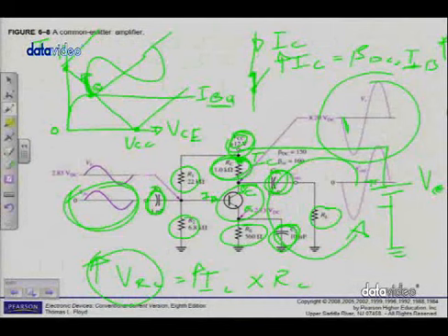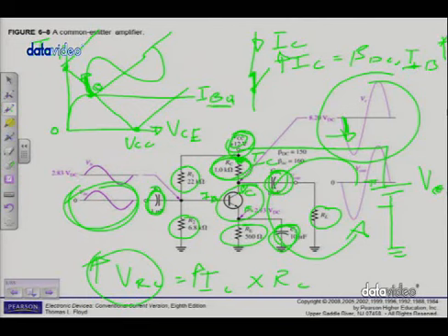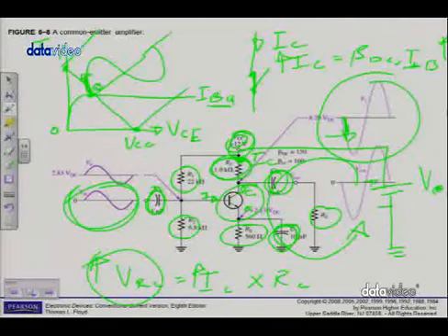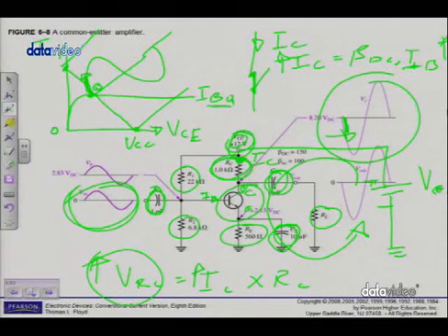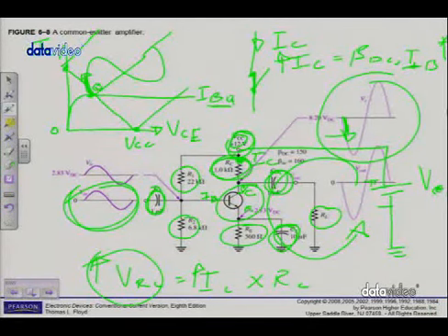And I can see it here. Look at this output signal of mine. What's happening? It's moving in the opposite direction. It's amplified, but it's moving in the opposite direction because of Ohm's law and Kirchhoff's laws. And that is why the input and output signal of a common emitter amplifier is 180 degrees out of phase. It's called phase inversion. All right. Now this phase inversion is also discussed on page 264. Please mark it NB. You have to understand this because this brings together a lot of electronic knowledge, if you can understand this.